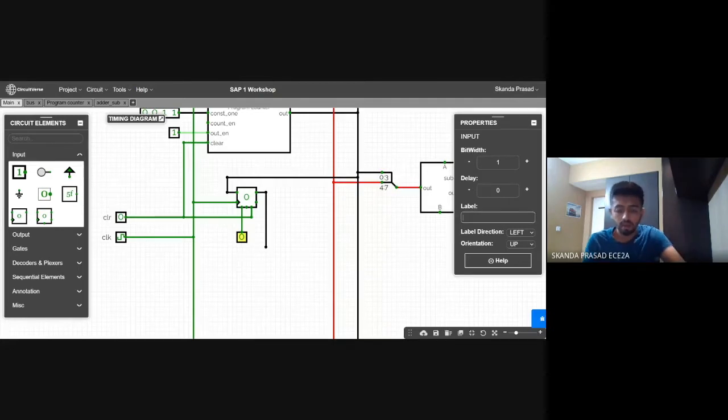I would request you to name it as I name it so that there is no confusion. It is an active low register. Most of them you've seen are tri-state registers, right? You give an enable. If it is 0, it is not enabled. If it is 1, it is enabled. But due to the practicality of the ICs or the chips which you use, the manufacturers build it with active low signals. So this is an active low signal.